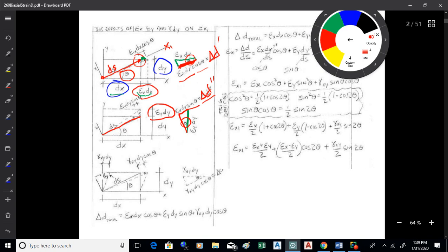And that was so much fun, I'm going to do it one more time because I've got the shear strain right here. If I apply that shear strain and change that angle, I'm going to get a delta up top there that's gamma xy times dy. The shear strain times dy. That should be equivalent right there. Pull out my little triangle.